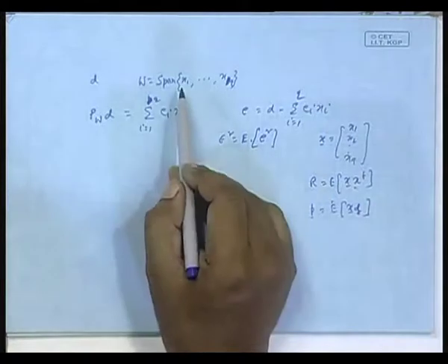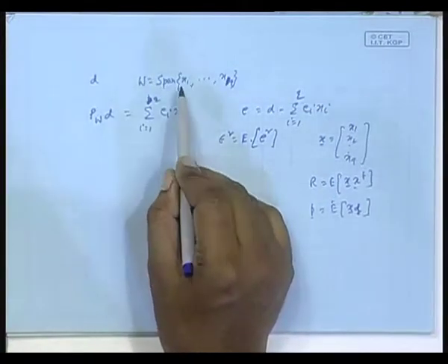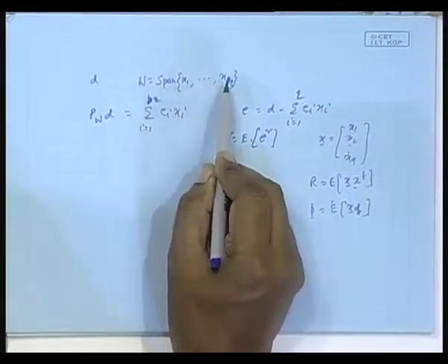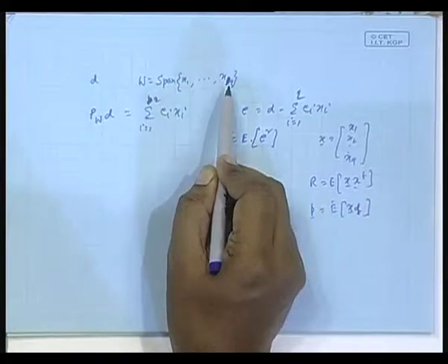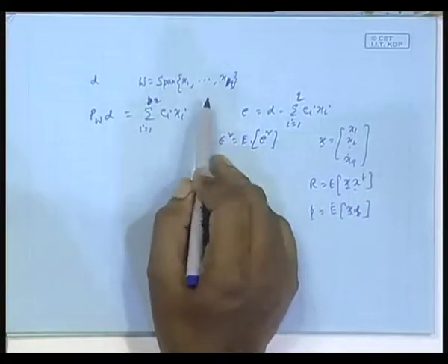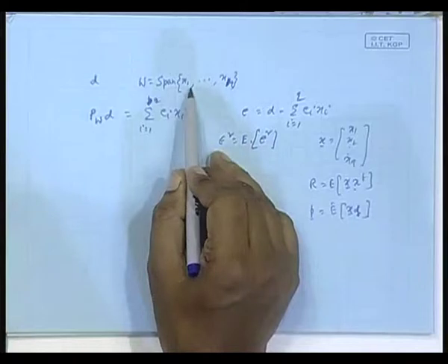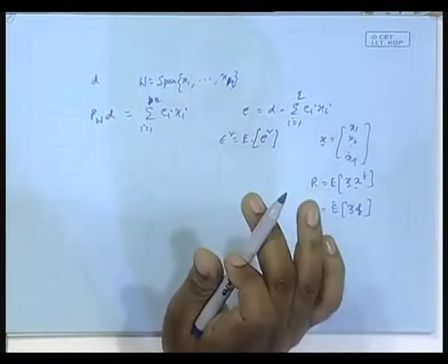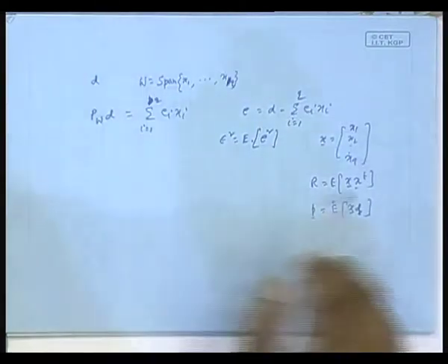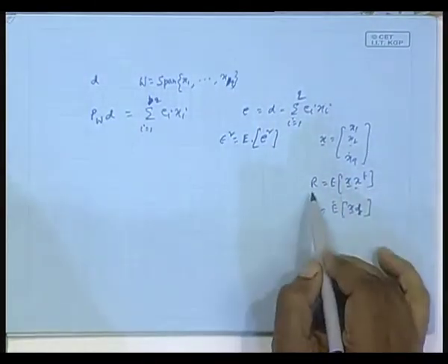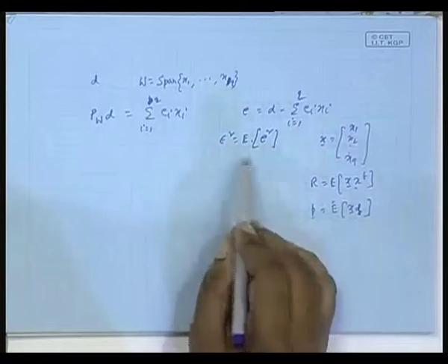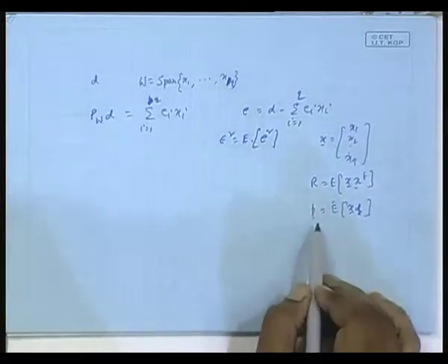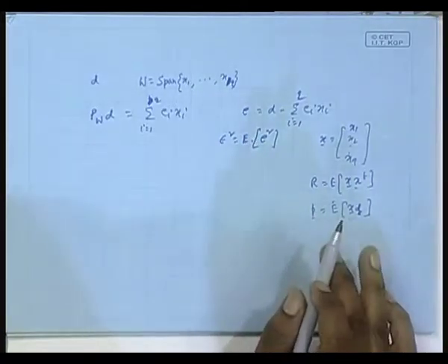You understand? In the optimal filter case, we had the variables x n minus 1 up to x n minus q or whatever. Instead of that, I am considering a little more general case, just q independent, meaning q defined, random variables x1 to xq. But the treatment will be the same. The optimal filter coefficient vector will be R inverse P, isn't it? How did you obtain that?